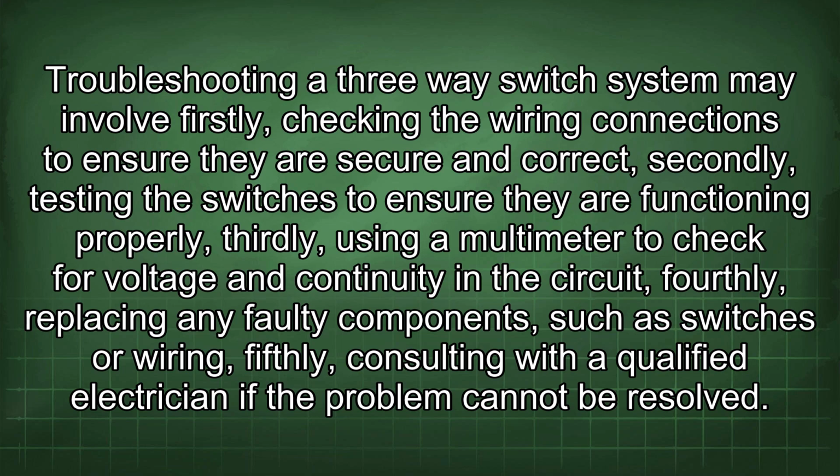Troubleshooting a three-way switch system may involve, firstly, checking the wiring connections to ensure they are secure and correct. Secondly, testing the switches to ensure they are functioning properly.